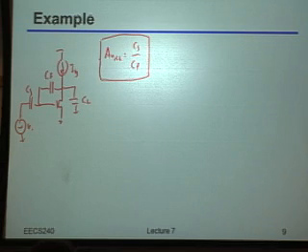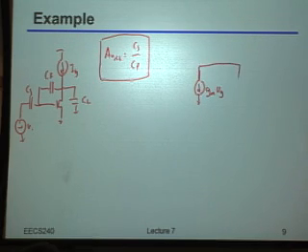Okay. So now let's start thinking about how we're actually going to get the noise performance of this particular amplifier. As usual, what's the first step? Yeah, small signal model. Let's go ahead and draw that. As usual, I'm going to have some GM from the amplifier. Let me call that GM-VG. There's, of course, going to be some capacitance at the output, CL.